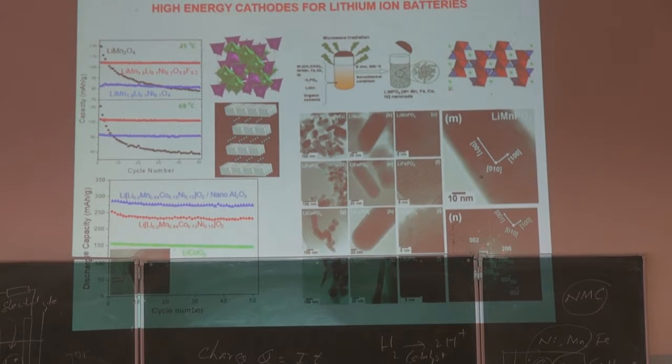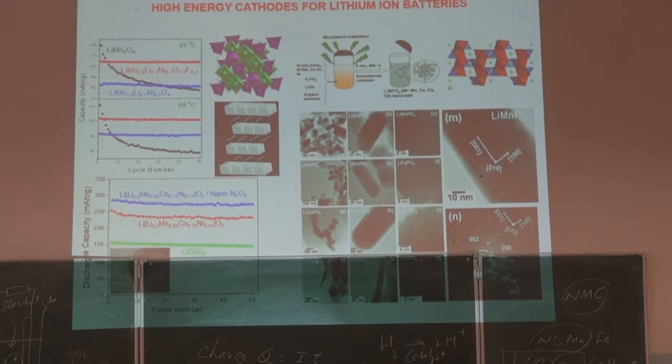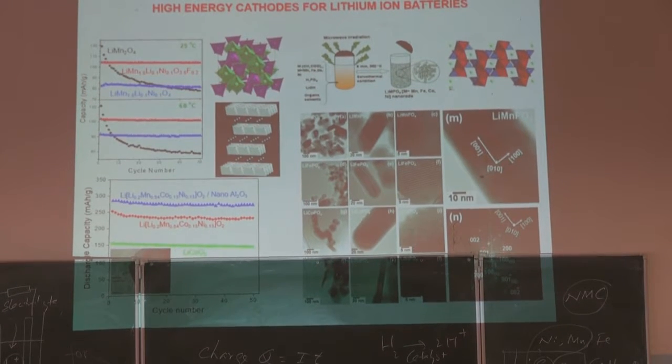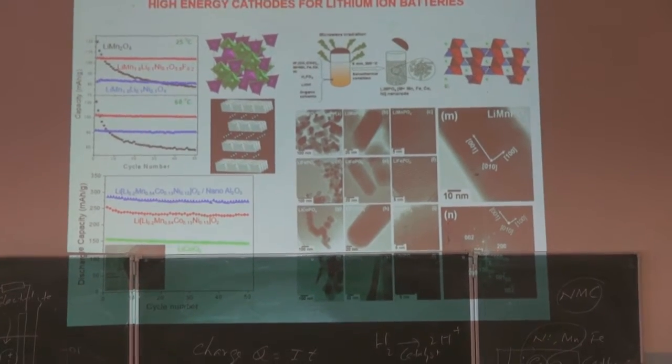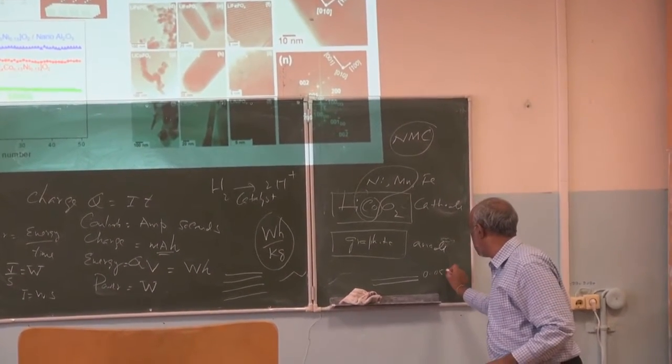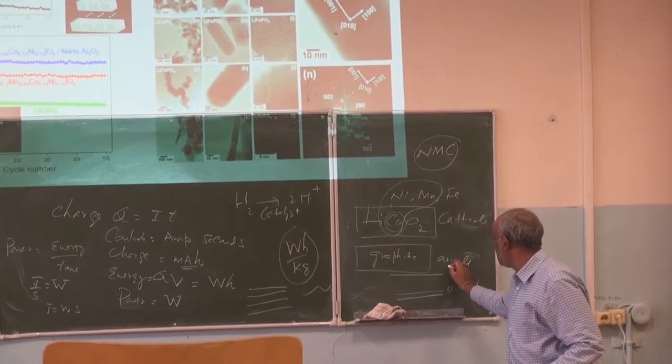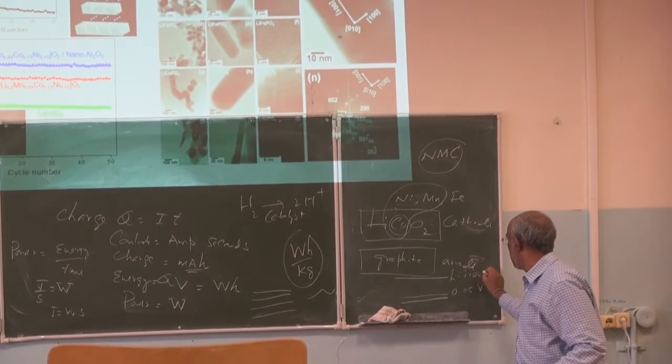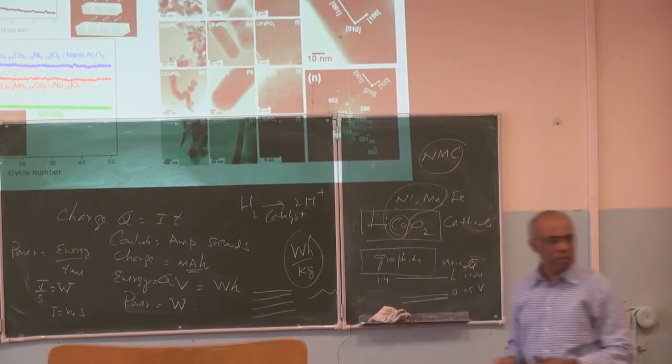But now there is some new work on lithium titanate. The problem with lithium titanate is that the anode voltage is high, so that means your voltage difference is smaller. But there's one advantage compared with materials close to 0 volts. Graphite has about 0.5 volts or so, and this lithium titanate has about 1.4 volts.